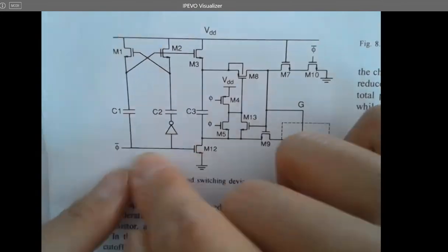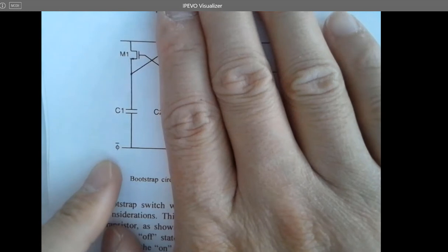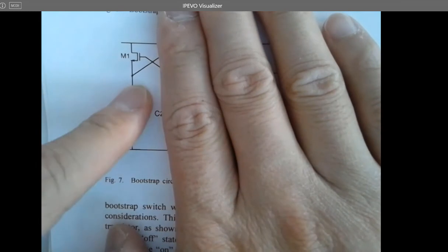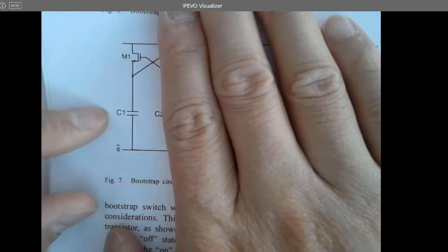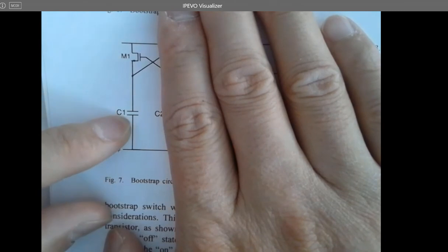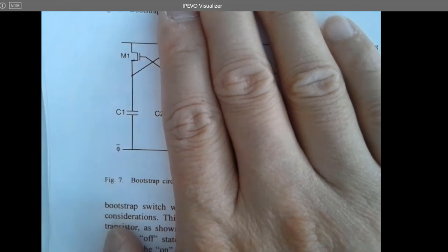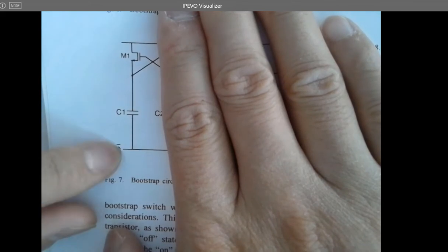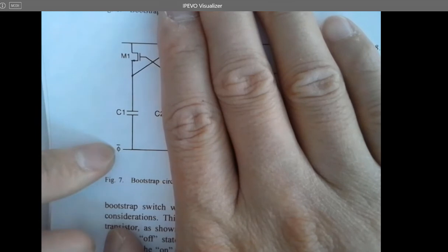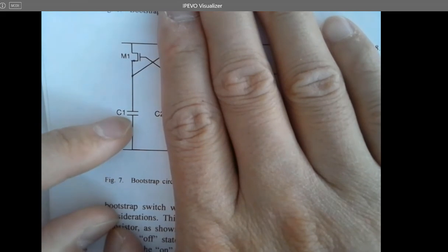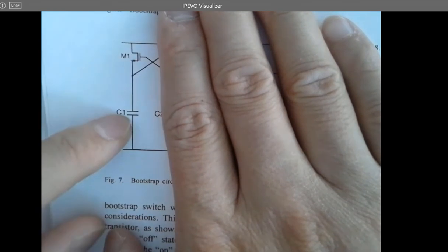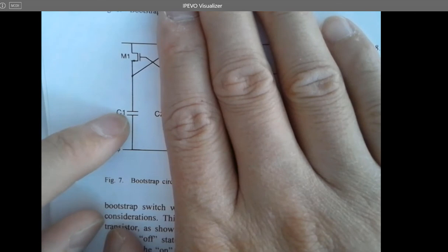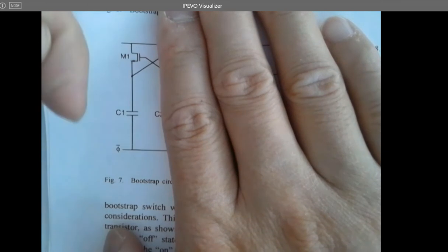Here's the charge pump. If we just do not look at all the other circuits right now, just look at this part, and you can imagine that as what I just told you guys last week. Whenever you are analyzing the charge pump, imagine that if you pull this low, it only happens at that transitioning period. When this is being pulled low, it's pulling positive charges to this direction, right? It's pulling charges down or pulling charges out from the bottom plate. And what's going to happen is it's going to attract the electrons. Go to where?